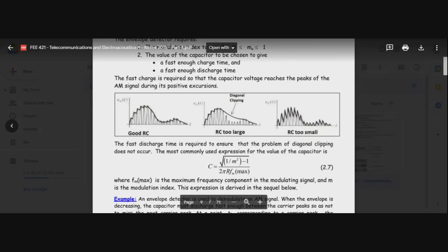But usually, when you take this envelope detector and you apply it to an AM signal, you will find that you can actually hear the output reasonably well. The ears can hear. The ears will do the low pass filtering, so that you don't hear those spikes. If you like, you say that those spikes will not cut the ear. They'll be smoothened out. All right.